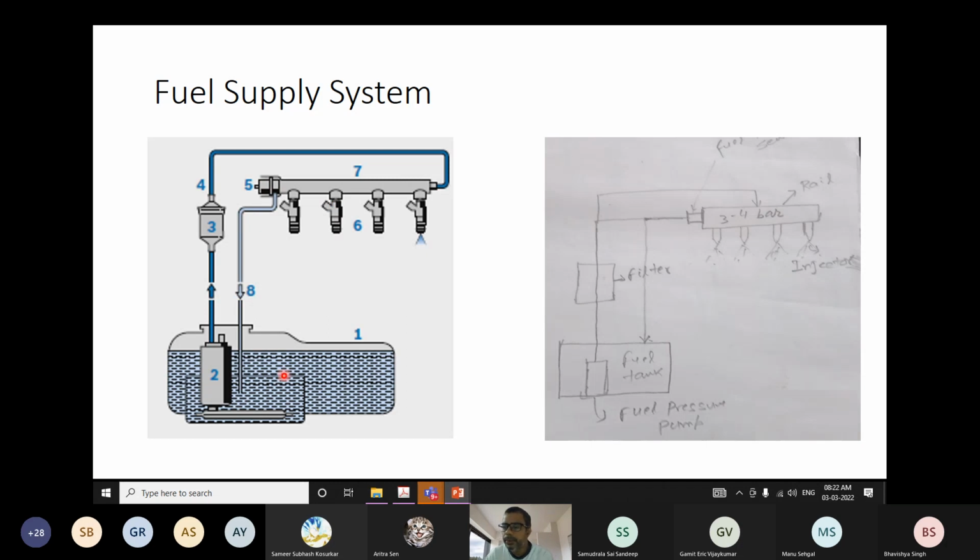So that is the fuel line system in the port fuel injection system. You have to always remember, or at least know, that in the PFI system the fuel injection pressure is a constant parameter for a given engine. However, from engine to engine there might be slight changes, but if two or more engines have MPFI fuel technology, their fuel injection pressure is roughly going to vary from 3 to 5 bar. That is the fuel injection pressure range.